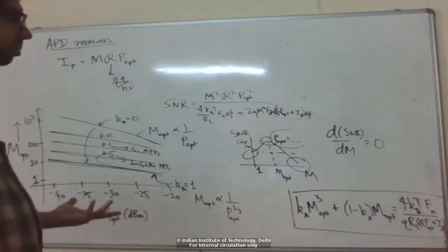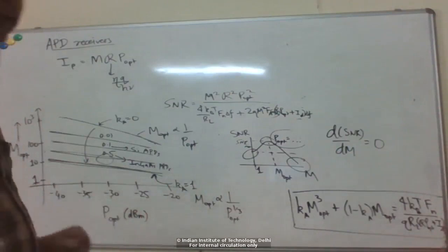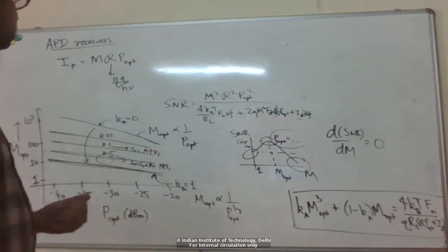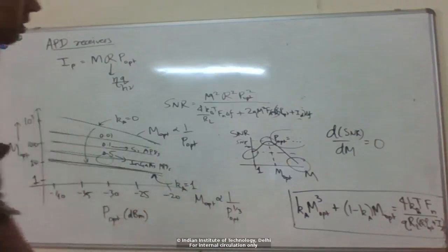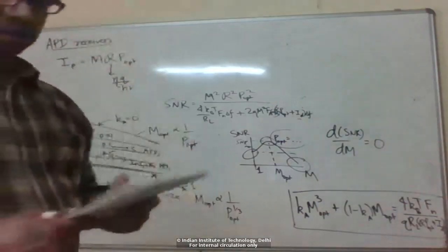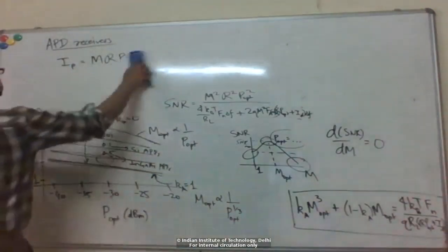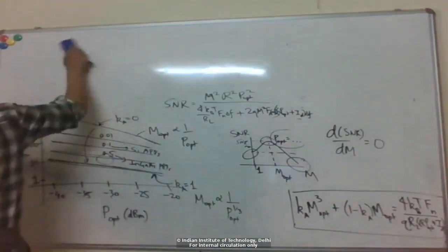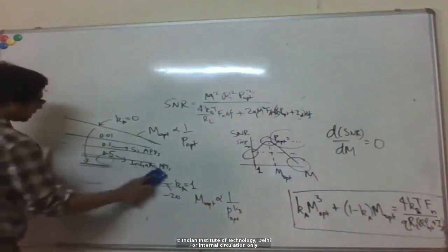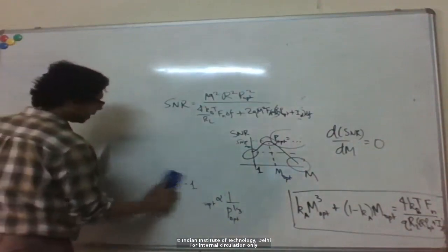So you might have heard, for example, that typically we want a bit error rate less than 10 to the minus 9, right? Which means 1 out of a billion bits are in error. So how does this SNR translate to the bit error rate? Let's briefly see how the SNR translates to the BER performance on the link.